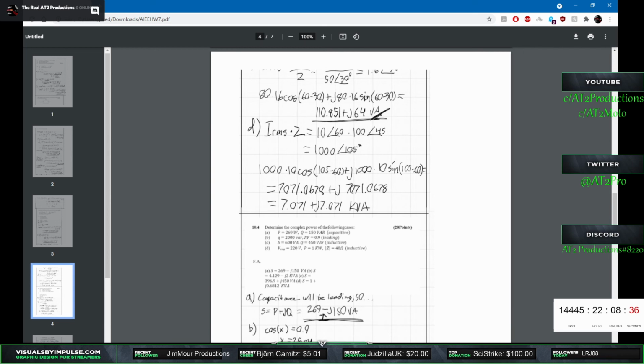Reconnected the motor, started up the drive, left the braking resistor off. Started up fine, ran fine. So now let's do this. Checked resistance across that DBR. We're reading 51.8 ohms. All right, let's see what it's supposed to be. Found the model number on the resistor pack, checked the settings from the logic of the drive. It is supposed to be 100 ohms at 500 watts is the rating of that device. Again, we were reading 51.